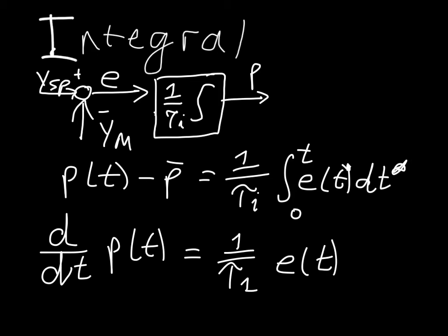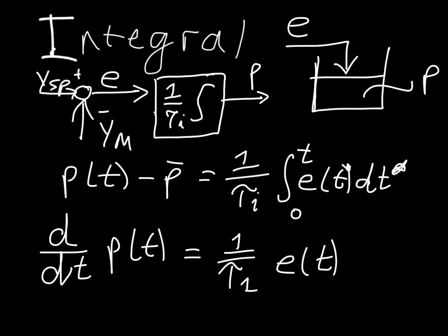It's always useful to have a model for how these things work. And my ever-present model for integral is just a closed vessel. And so there we can say that the integral here is actually the error integrated. And it's a little bit difficult to think about this just as a tank, because obviously when the error becomes negative, that's actually removing stuff out of the tank. But as soon as these balance out, as soon as we don't have any error, the proportional amount will remain the same.